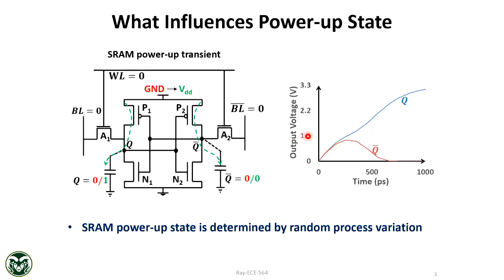Okay, so that's an interesting topic. Still, there are a lot of things that can be done. For example, every chip should have a unique ID that nobody can change, and you can do that too, because the power-up state is used as a fingerprint of a chip, which comes from process variation. But what we are doing is more like changing it for some useful purposes. For example, read-only memory, which will be very, very tolerant to other variations.